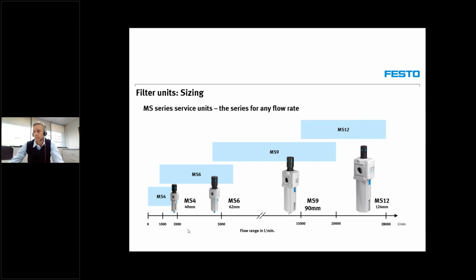Another question before I go off. When you have a large diameter or larger diameter of, say, linear actuator, is there a guideline for the size of connection or your air supply? I've experienced some problems in the past where the lines are undersized and you have a jerking motion because the air compressed in the cylinder builds up, but then when it starts moving, it drops. So you have this variation inside the cylinder.